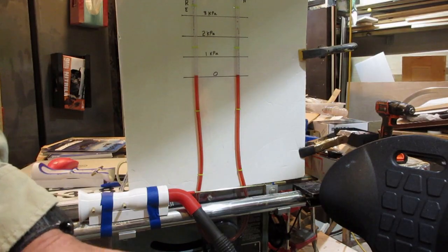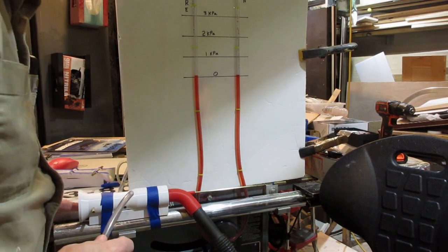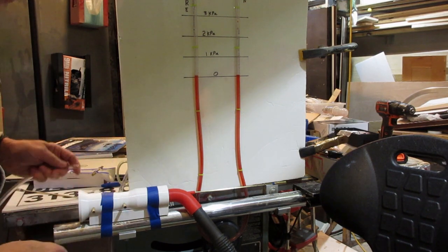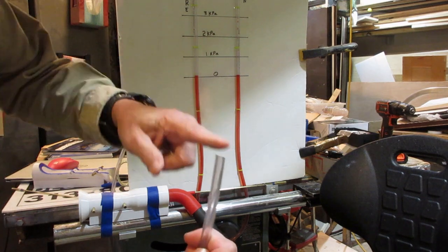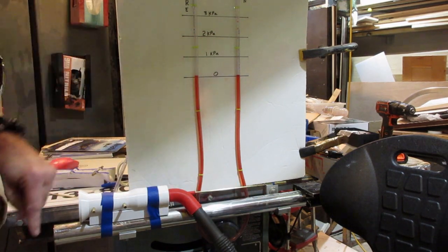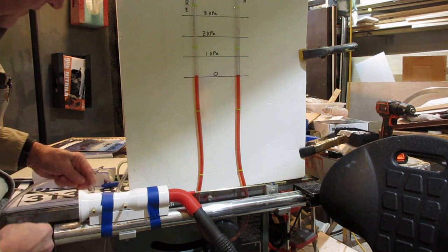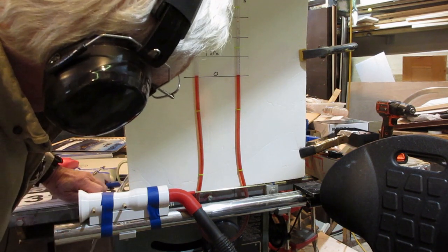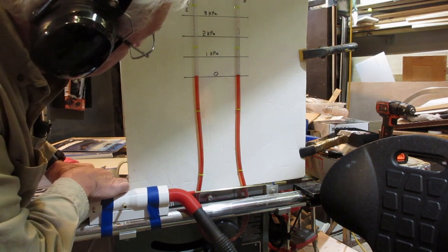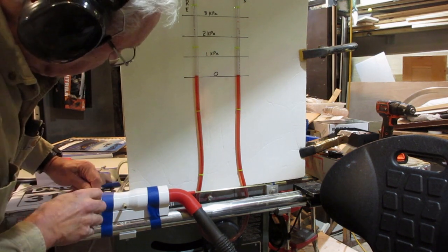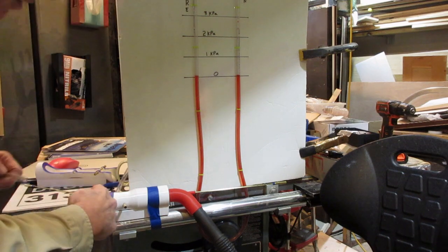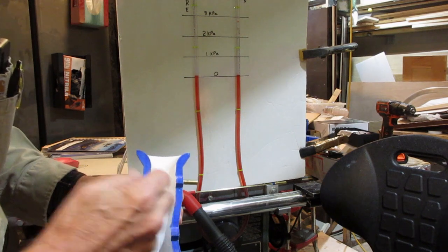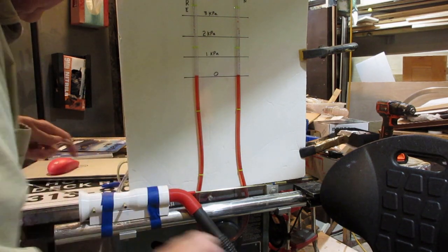So first we're going to look at the pitot pressure, which according to Bernoulli should be constant because that's the total pressure. We'll start by using the probes that are built into the Venturi, and as you can see here, just connected to atmosphere, the total pressure is 0 on our manometer. Plugging into the upstream or first pitot tube, we get, again, almost the same reading from our U-tube manometer, as you'd expect from Bernoulli's theorem.